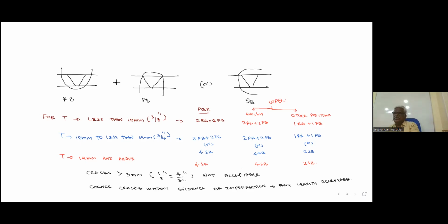20%. Then coming to the hot tapping. So hot tapping is covered in API 2201. We have seen PCC 2 also. What are the two major problems of hot tapping? Burn through and cracking.